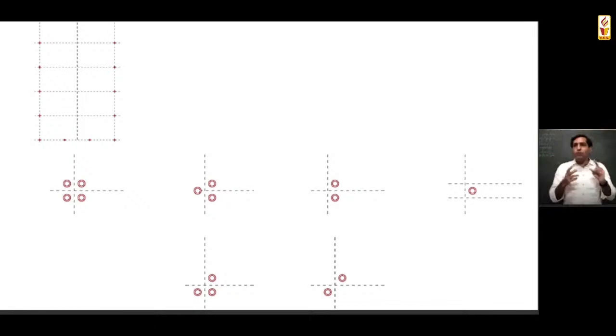Now, obviously, the 4 one becomes the most convenient, simply because you can cross members easily. The more you drill the bamboo, the weaker it becomes. So apart from bundling the bamboo to take care of its low modulus of elasticity, in most structures you'll find it bundled also because different directions come there. It is very easy to detail when there is a 4. 3 is slightly difficult. So I have put all the combinations for you right now to think. Go next.